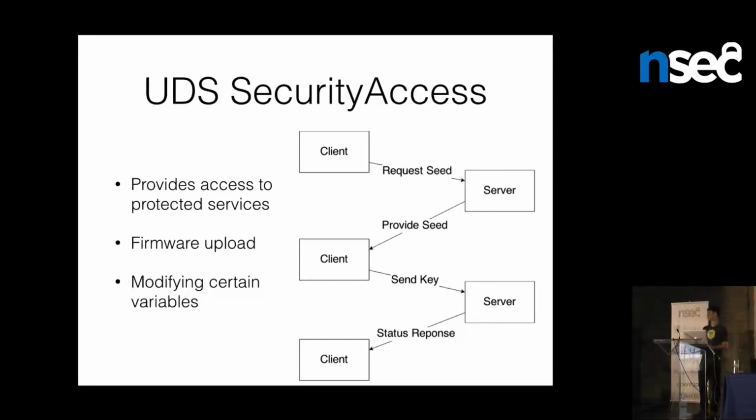The way that this works is a really simple seed-key exchange, which you've probably seen before for stuff on not cars. Basically, the client is going to request a seed. The server will send one back, and based on that seed, the client will generate a key. It sends that to the server, and it comes back with, hey, you were allowed in, or no, that was an invalid key, or you've tried too many times, sorry, don't try again. Doesn't look so bad at first, but the problem is that the seed is fixed for that controller. And so that's the first kind of red flag, and that means that the key is also fixed.